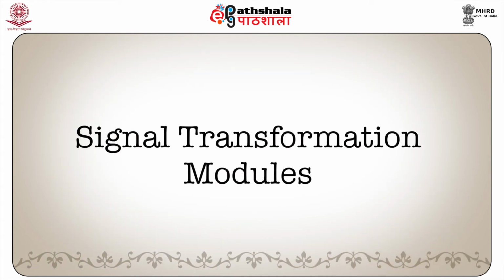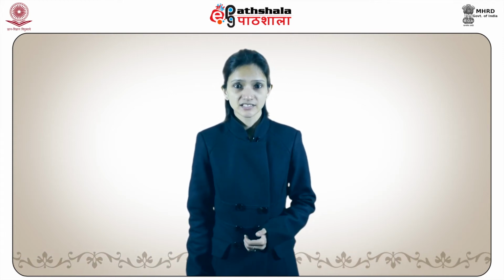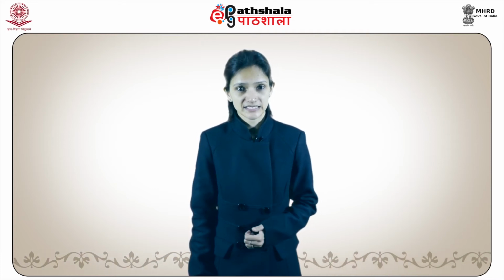Signal transformation modules. The signal transformation module receives information from the detector, electrically converts it into a more meaningful form, and then presents it to the output transducer. The detector used and the final form of the desired information determine the electronic composition of this module. Module components range from a single resistor for simple current to voltage conversion to a complex microprocessor that has a variety of signal processing capabilities.